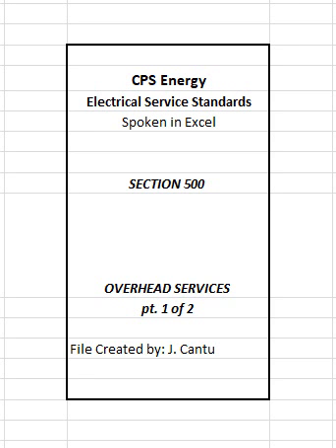501 Downtown network system. Overhead services are not available in the area served by the downtown network system, which is generally in the San Antonio Central Business District. Only underground services will be allowed from the downtown network system. Customer may contact the CPS Energy customer service representative for the geographical boundaries of the downtown network system and to review service options from the downtown network system, refer to Section 1100.